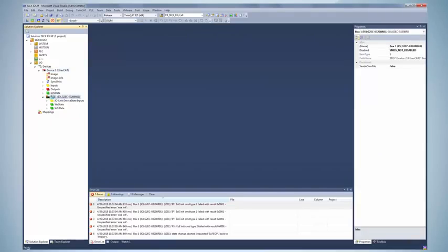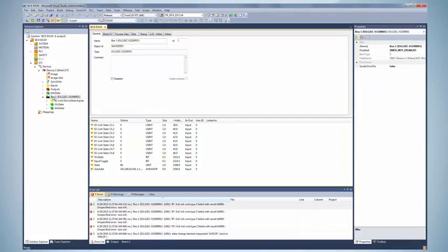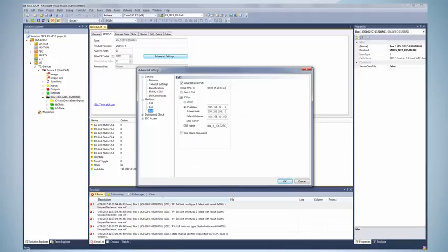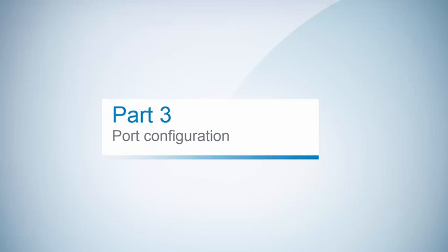The first step is setting the EOE feature. Select the I/O link master in the EtherCAT tab, Advanced Settings, Mailbox, EOE. As default, EOE is activated. If you do not want to use the EOE feature, the checkbox shall be deactivated. If you want to use the feature, a valid IP address needs to be set. In this example, 192.168.10.50.